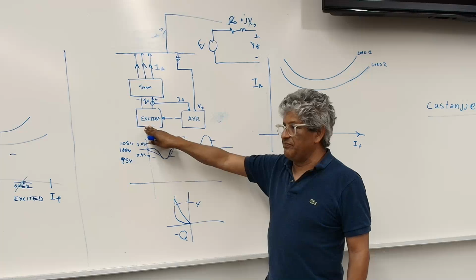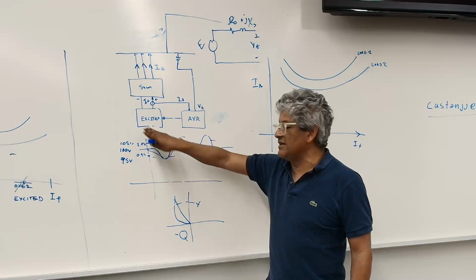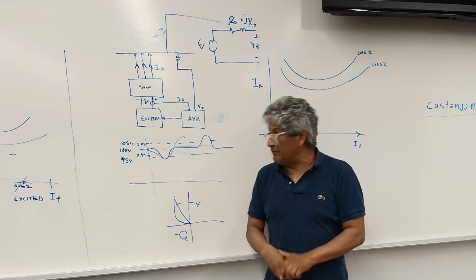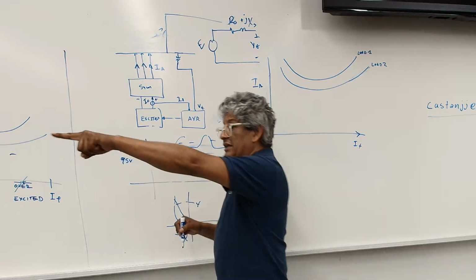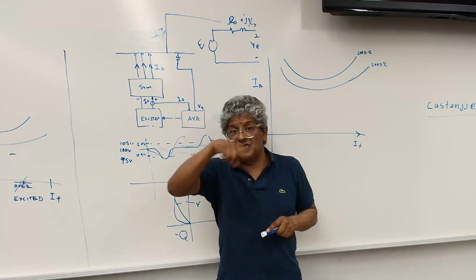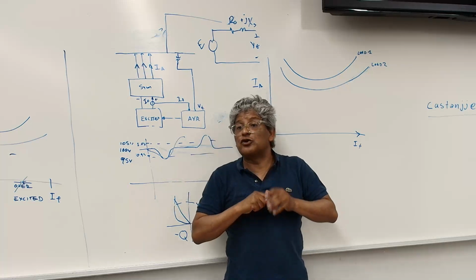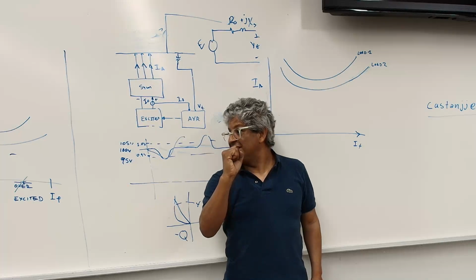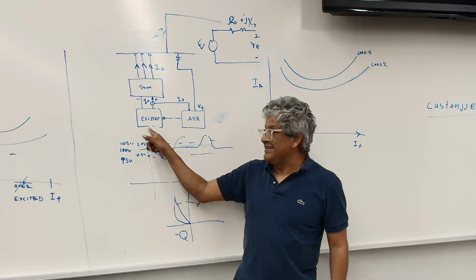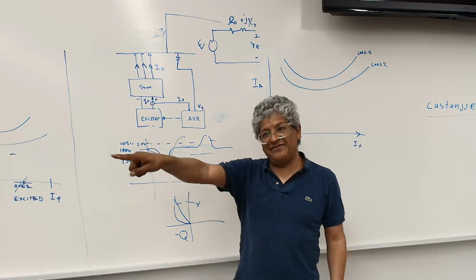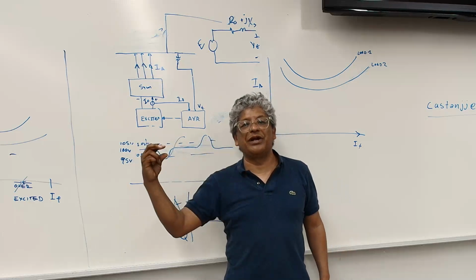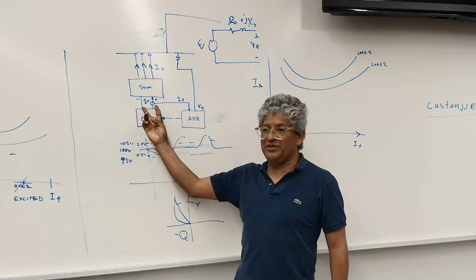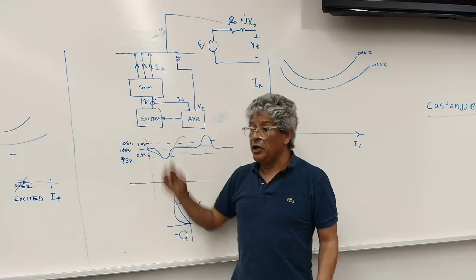The excitations, and that's the last thing I mentioned. Excitation speed is what really changed. It used to be like this. If you have your machine there, your motor, the shaft of the synchronous motor, they would put a DC motor connected to that shaft. So the DC source that you guys have there, it was a DC motor connected to the shaft. The generator was running the DC motor to provide you with this DC voltage right here.